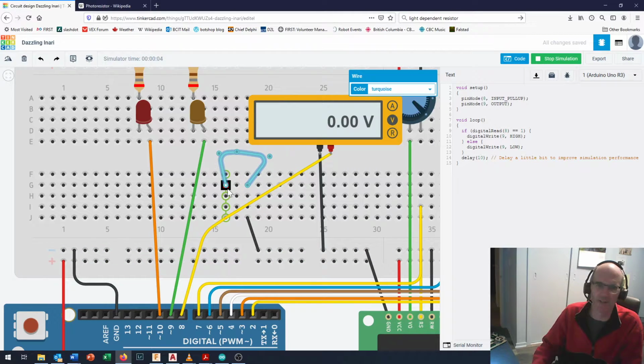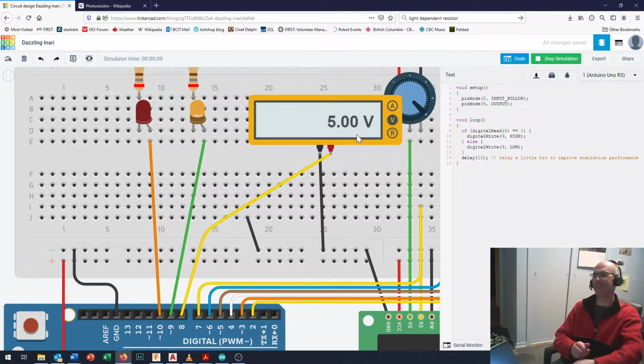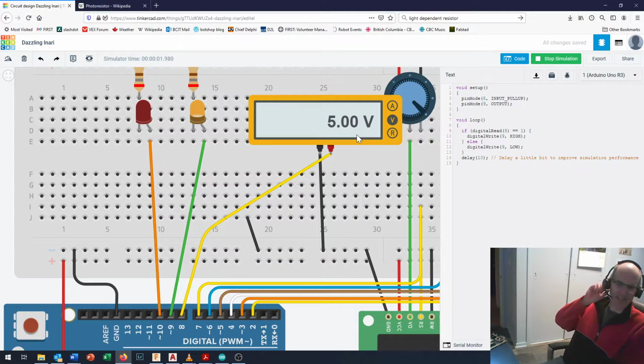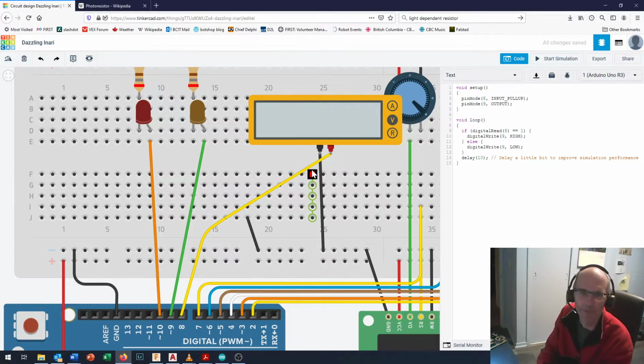It's like pushing this down on the switch, and we're at 0 volts on this pin, so we've got no light coming out of the LED. And if I want to adjust my wiring, I stop the simulation and I unplug that wire. We delete that wire and we start the simulation. You just unplug it in the real world. TinkerCAD's giving me a little bit of grief right there. So, and now it's up at 5 volts and the LED comes on. Okay, I'm going to stop that simulation and disconnect this lead.